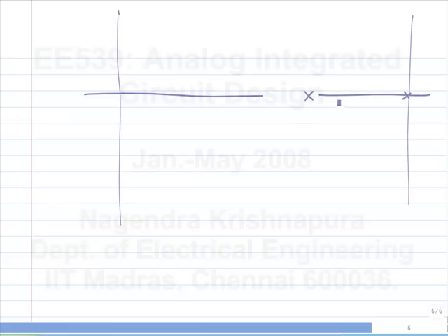Instead of this, let's say you start off with something which has some stuff like this. Then the phase margin will be very poor. It is valid, but it will give you a very poor result because this is below the unity gain frequency. Now we can't even define the unity gain frequency properly if you have complex poles.